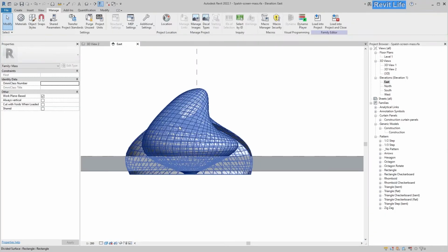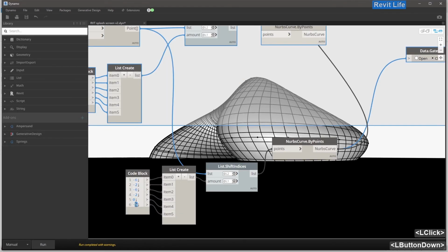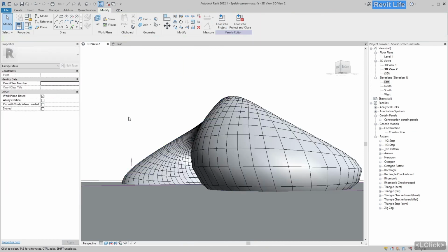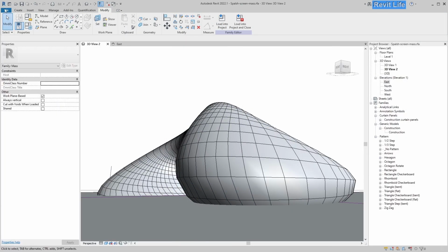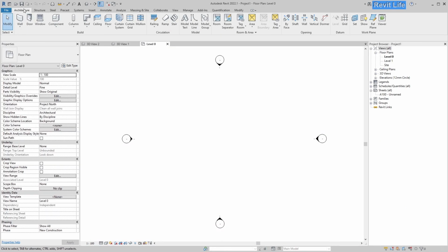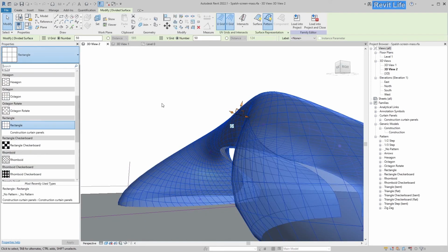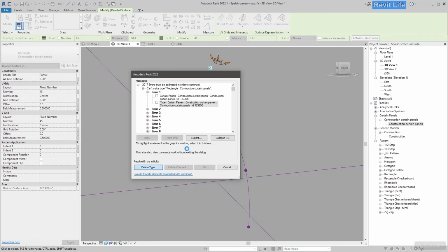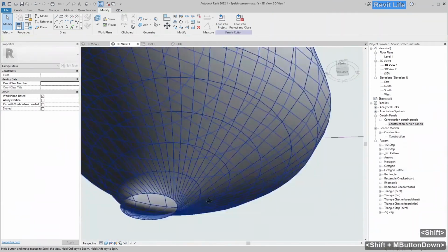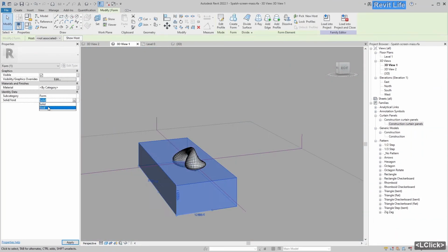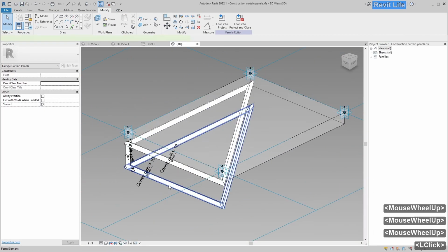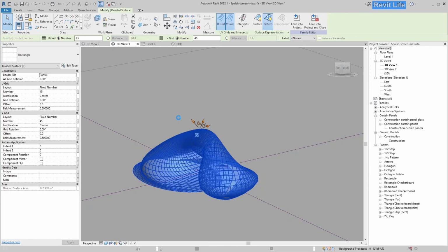surface. And again I'm trying to add this surface to the Revit mesh family, because not all surfaces are accepted by the form by loft cross-section nodes in Dynamo. Not every surface gets exported. So that is also a problem, because I can get the shape and the grid lines as close as possible in the Dynamo 3D viewer, but I cannot export them for some reason. So I have to readjust the surface and readjust the grid so I can export it.